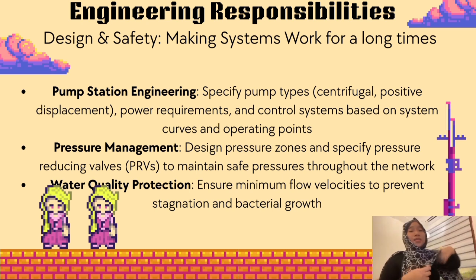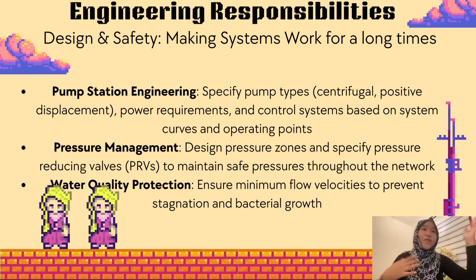From my slide, there's three key points, which is pump station engineering, pressure management, and water quality protection. For the first key point, which is pump station engineering, it mentions that specified pump types like centrifugal, positive displacement, power requirements, and control system based on system curve and operating points. For the second point, which is pressure management, design pressure zones and specify pressure reducing valve PRVs to maintain safe pressures throughout the network. The last key point for design and safety, which is water quality protection, ensure minimum flow velocities to prevent stagnation and bacterial growth.